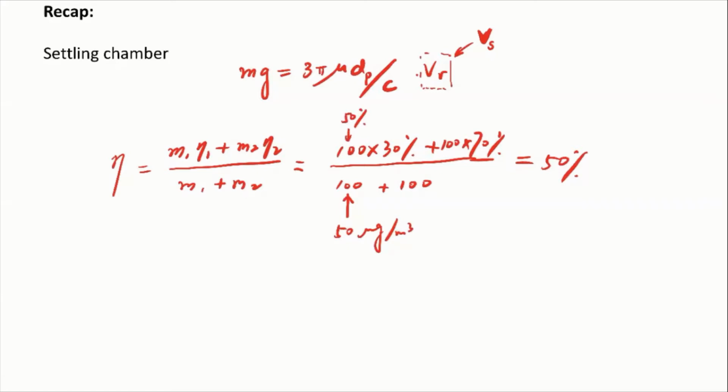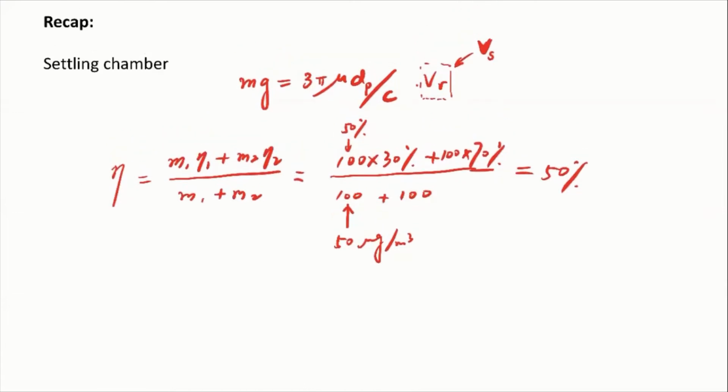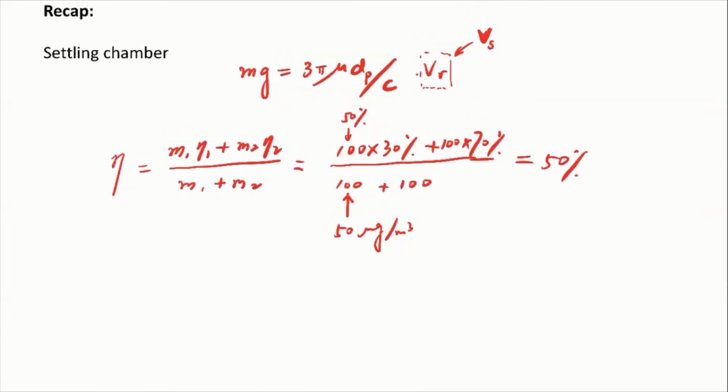Basically it's not 100%, because you're not achieving 100% for either of the sides. So that's why the overall efficiency has to be below 100%, okay? This is just a brief calculation in terms of the particle removal efficiency. I think in this class, in the calculation of the cyclone, you'll get more understanding regarding this overall removal efficiency.